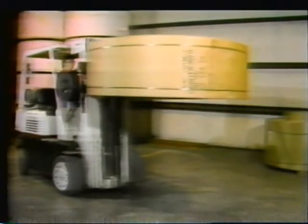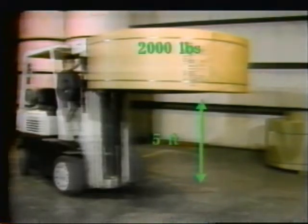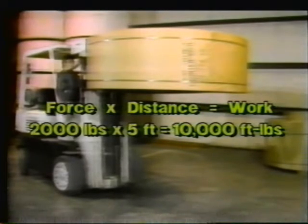Let's take a look at the work this forklift is performing. If the forklift exerts a force of 2,000 pounds over a distance of 5 feet, then, according to our equation, we have 2,000 pounds of force times a distance of 5 feet equals 10,000 foot-pounds of work.